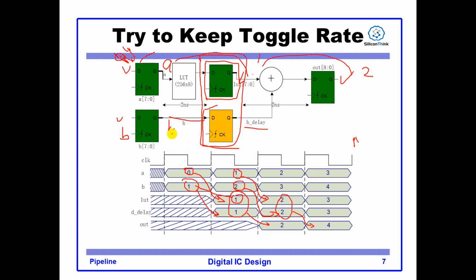So this will be the first pipe, then the second pipe. For all the inputs to the output, the pipe latency is the same. Then you can maximize the efficiency of the circuit.